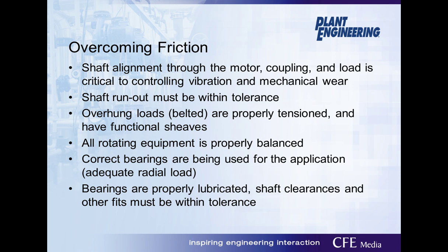mechanical wear. All manufacturing tolerances must be met, including shaft runout, bearing housing, bearing fit, and rotor balancing, among others. Correct bearings must be used for the application. For instance, standard ball bearings would be used for direct coupled loads or lower torque belted or sheave loads. Roller bearings would be more appropriate for belted applications with higher radial loads.